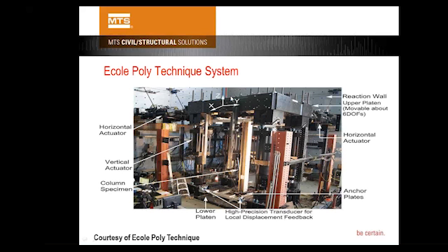So we had a lot of problems with the stability issue with this system, and we needed to slow down the test significantly to overcome that friction problem. Even though we slowed down so much, we still needed to come up with a friction compensation method. We simulated a 10-second earthquake, and it took about 48 hours. In comparison, you will see the hybrid simulation test will be much faster.